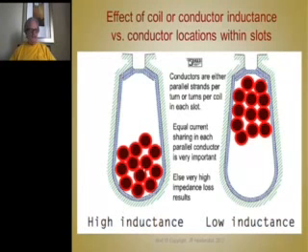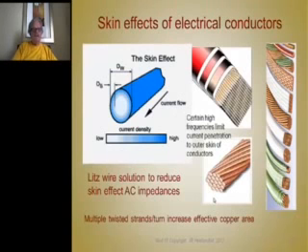That balances out the inductance situation very nicely. But if these are parallel strands for one turn, you can get variation in inductance from each of these strands, from this one to this one. So sometimes you have to use Litz wire or use some transposing of these coils.